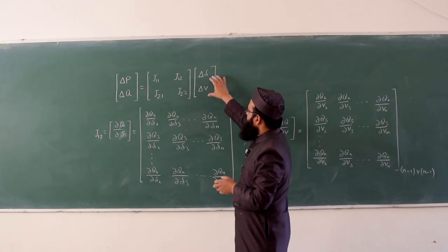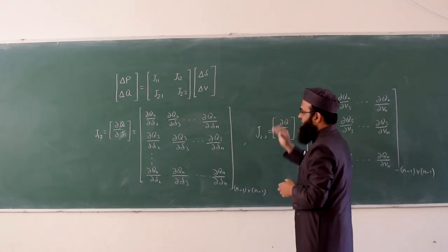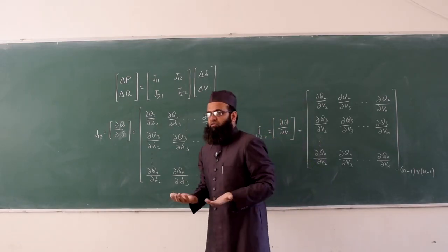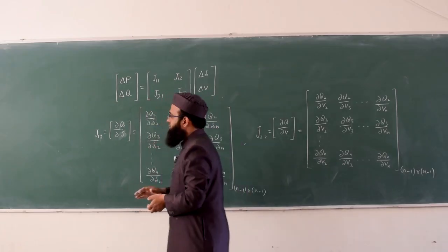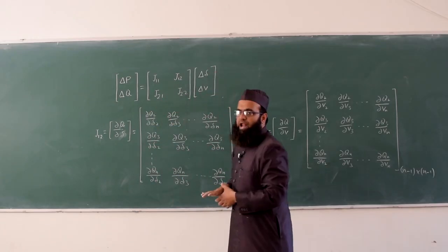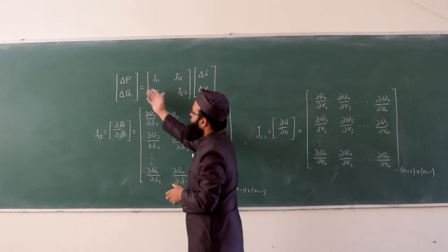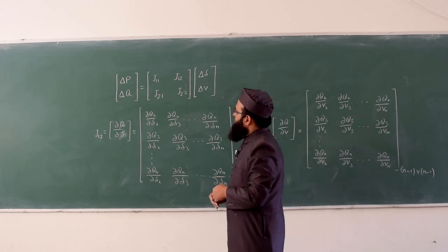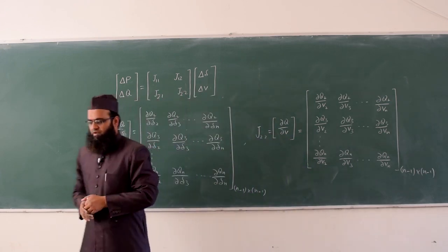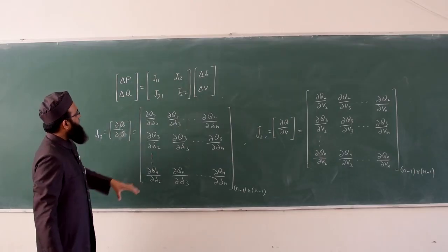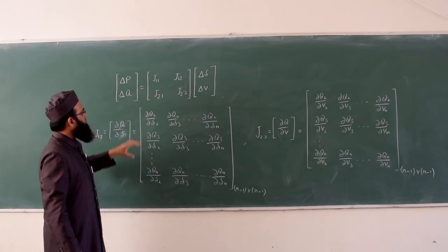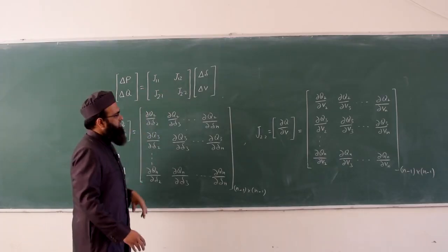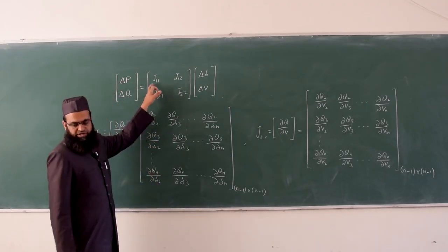So, on the right hand side, del delta and del V vectors are unknowns, corrections required. These quantities are required to be calculated, and the corresponding unknowns will be updated. Now we will discuss the simplified version of J11, J22, how to calculate J11, J22, because it seems to be lengthy. So, we will try to simplify the calculations for the elements of the Jacobian matrix.